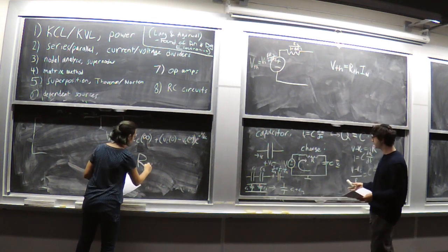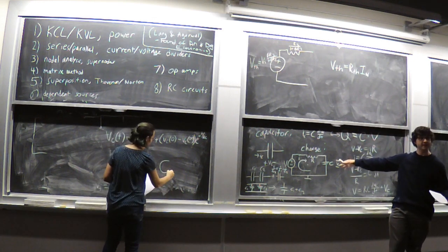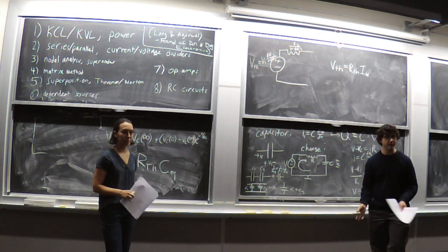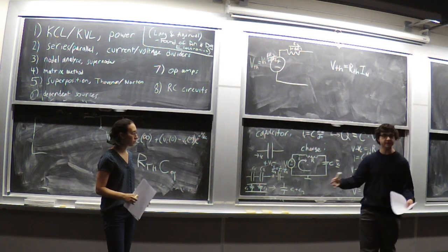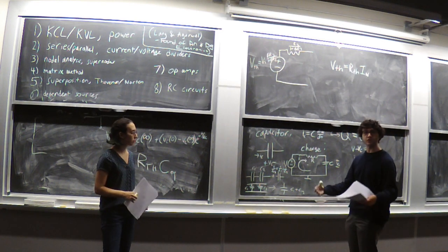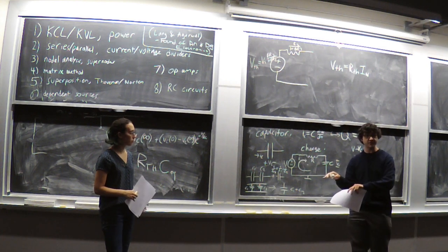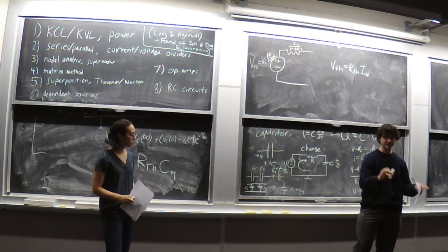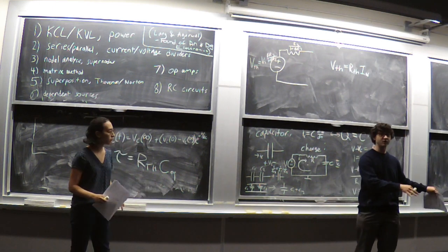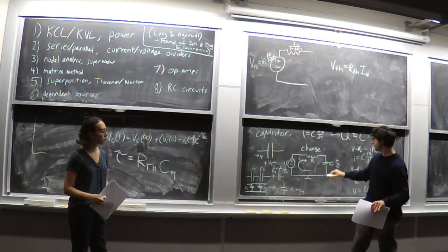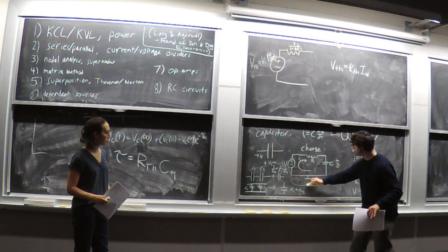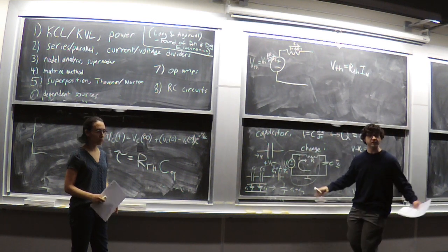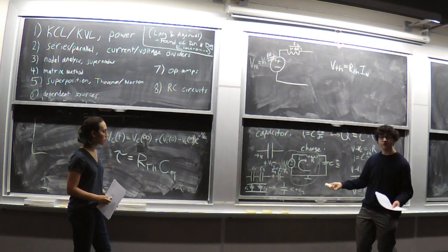And that actually brings us to the final point we were going to talk about, which is that sometimes if you want to analyze a circuit with a capacitor, if it's some really complicated network surrounding a capacitor, it might be hard to see what the time constant should be. And so one thing that you can do is isolate the capacitor, rip it out, and view the entire rest of the circuit with all of its linear pieces as a black box and solve for the Thevenin equivalent of all of that. Because as far as we're concerned, this voltage source in series with a resistor is a Thevenin equivalent. This could be any linear circuit we want, and then we attached it to a capacitor.